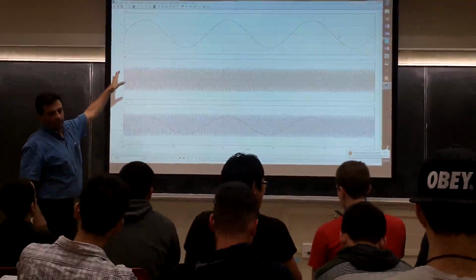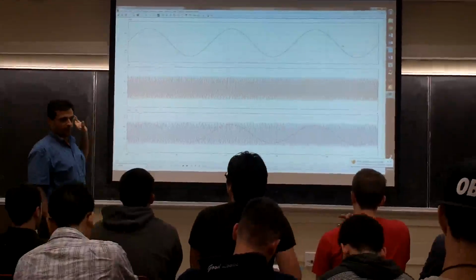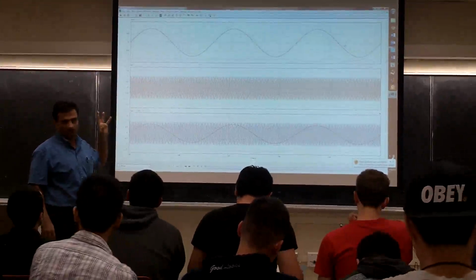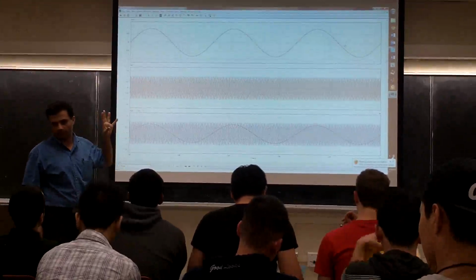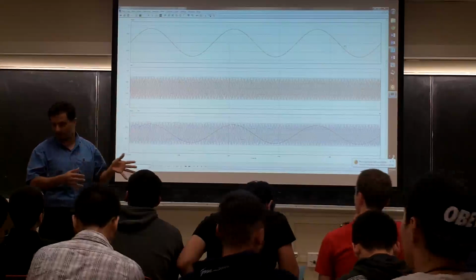This is a sine PWM. Remember what I proved here. For example, the V11 for the half bridge is MA times VDC over 2, and for the full bridge it is MA times VDC. And I went through that, similar triangles and those kinds of things.